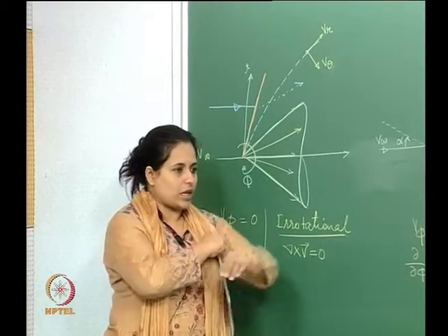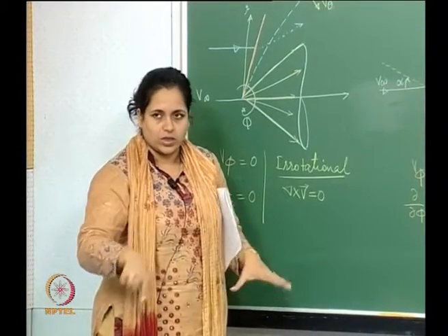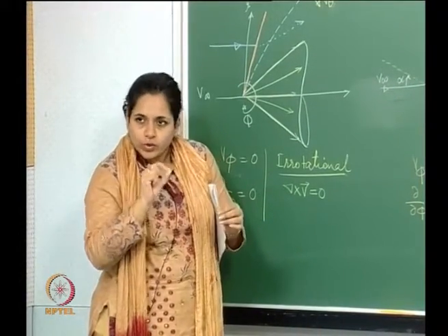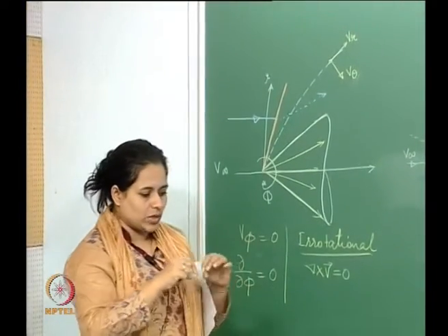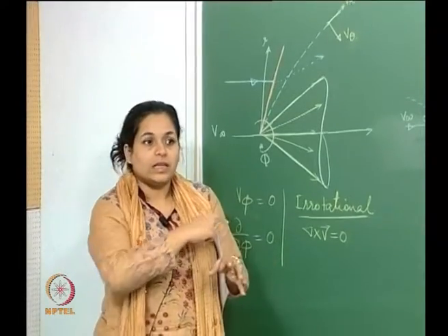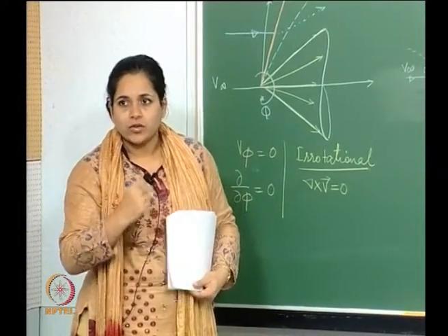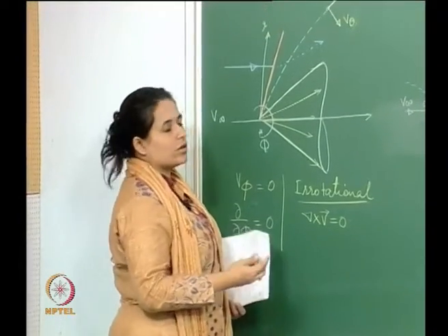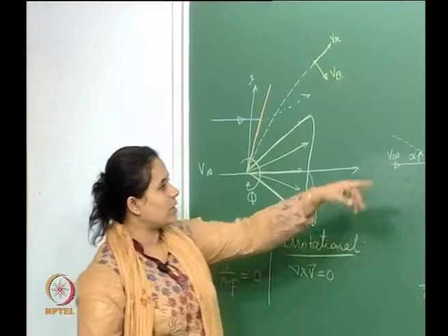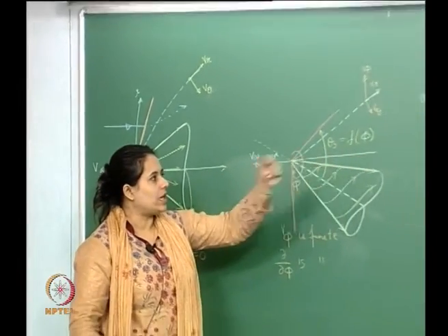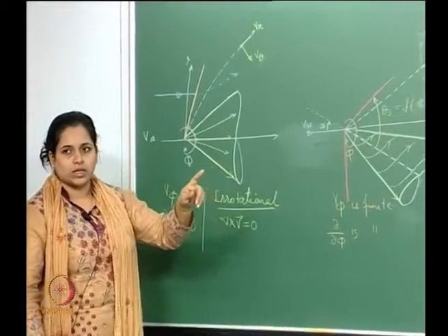So, if I take the vertex of the cone, all my radial lines are equally fanning out from this particular point. Right. So, when a streamline comes and moves in here, the angle of the shock does not change. Therefore, it is constant entropy, and hence we can use Crocco's theorem, del H0, del S 0, and hence it is irrotational. Here though, that is not the case.